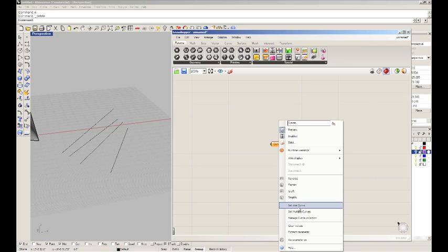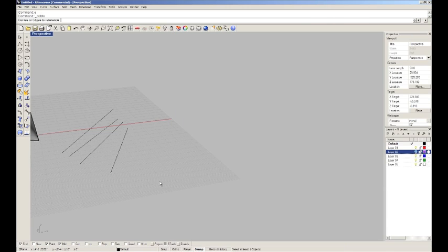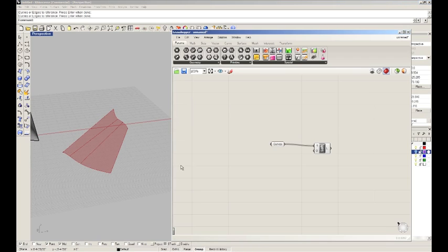So what you can do instead of setting one curve at a time is set multiple curves. I'm going to click on this, and then select these guys in order along the same edge. And you'll remember from when we were talking about lofting in the Rhino tutorials that it matters what order you select things in and also at what side you select them.